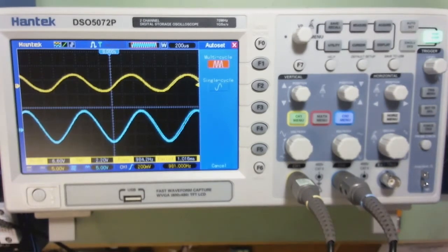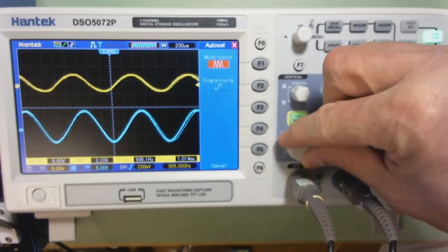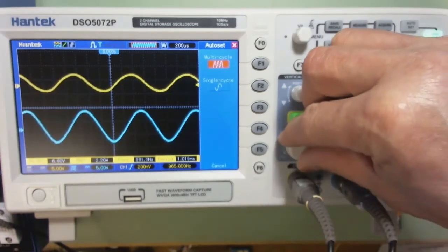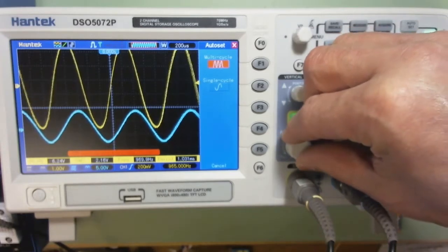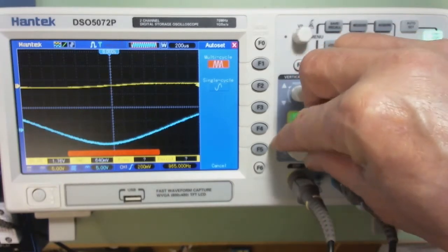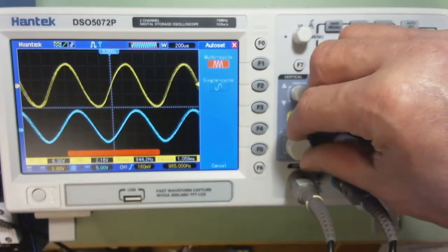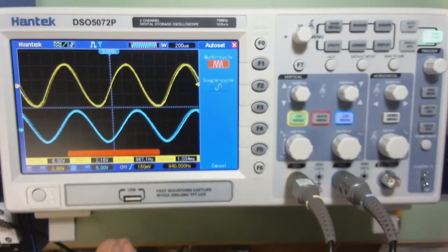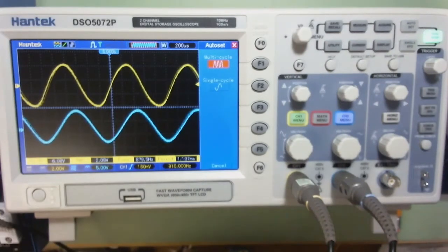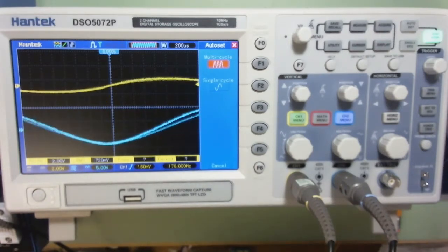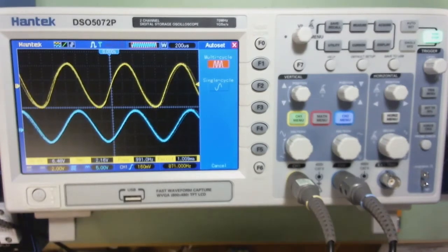So when you walk up to an oscilloscope, and this is just a measurement tool, if for instance I change this, oops. Come on, here we go. There we go. So you can see that yellow wave, I'm changing the amplitude of it pretty significantly with this. Now that's not physically changing the circuit, that's just changing the magnification. That's like looking at a map with a magnifying glass. Okay, it doesn't change the difference between two cities, it just changes your view of it.